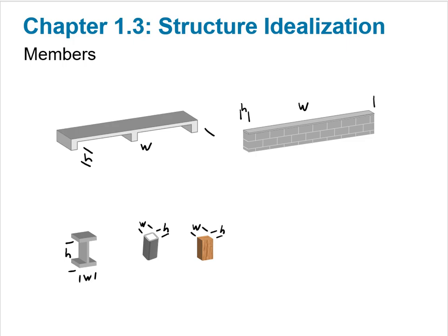thin lines. When a member experiences a net internal moment, there is a location in the cross-section that has zero strain. We call that location the neutral axis. Because that location doesn't get longer or shorter, it is the best location for our thin line idealization of the member.